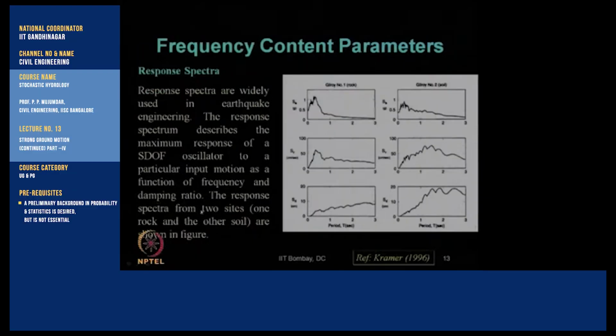Another function, frequency ratio. If you remember, in our other video course on soil dynamics, if you have gone through that video course, you will know that for a single degree of freedom system, if I want to find out its displacement at any point of time, it has to be expressed in terms of its static displacement or initial displacement, in terms of its damping ratio, and in terms of its frequency ratio, that is the applied frequency to the natural frequency of the entire system. So, the same thing we will see here also in a subsequent lecture.